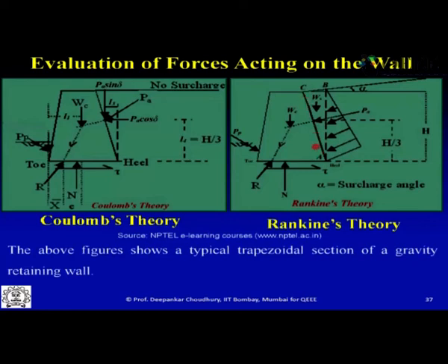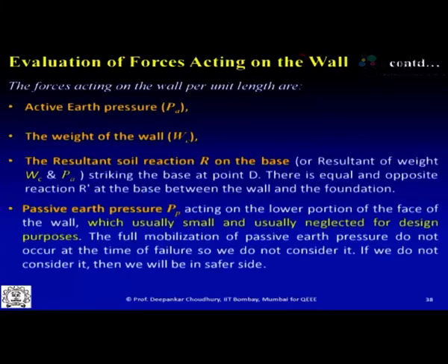And if it is an inclined wall, I have mentioned how to compute the resultant of this Rankine earth pressure and the force of that triangular portion and get the resultant earth pressure acting on the wall. So anyway, you can use Terzaghi's theory also for computation of earth pressure. Once you get the earth pressure, if it is for the active state for which you are going to design, and in most cases of retaining wall, as I said, it is for active state, the weight of the wall, WC, you have to find out.